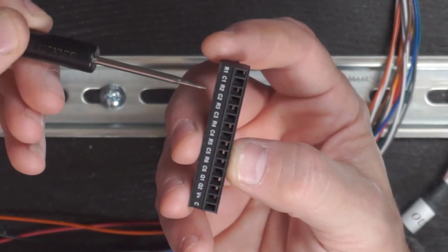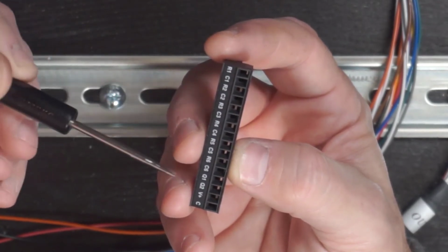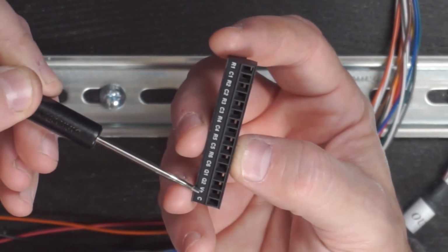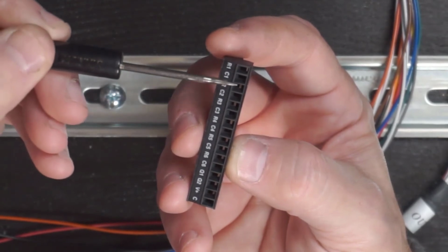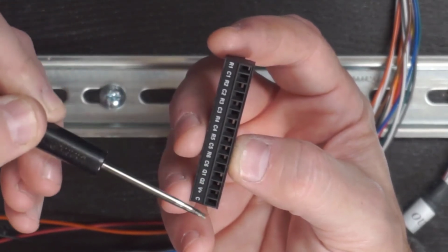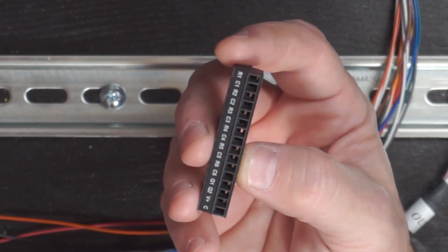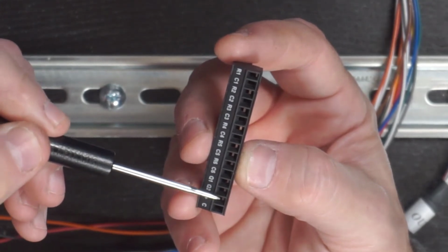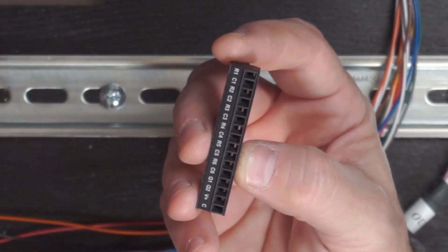However, the common wires for the relays, C1, C2, C3, all the way through C6, along with the V+ terminal here for the high-speed outputs, all need to be connected to 24 volts. That means we're going to need a jumper assembly connecting those particular pins, and I'll show you that in a little bit. But we'll just get started on the output side by connecting up our outputs as well as our relay signals, and then we'll come back to the jumper.